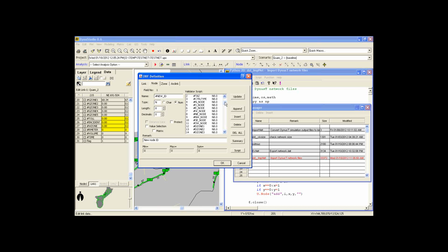In standard practice, for example when you're building a Synchro database or building other traffic analysis models, you do have that information, the node directional information. So here, I like to retain that information. Once you have this information entered, later on it will be easy to debug issues, or easy to import, export, and exchange information with other models and other data sources.